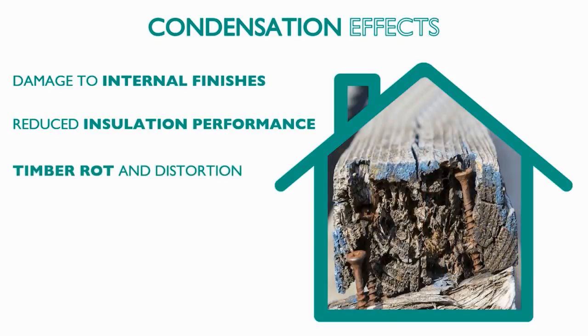In most cases, timber will begin to rot if the moisture content is above 20% for longer than 60 days. Rotten structural timbers will severely reduce the lifespan of a building, so it's critically important to ensure moisture is managed to avoid this. It's also important to remember that as timber absorbs moisture, it may well swell and distort due to expansion. The converse is also true. If the timber gets wet and swells during construction, it may subsequently shrink as it dries, which can also lead to problems.